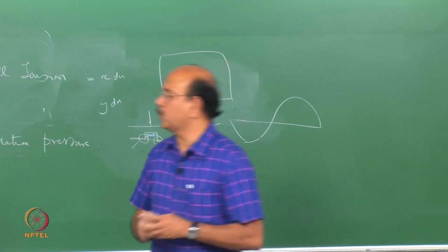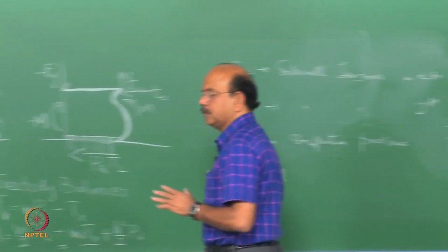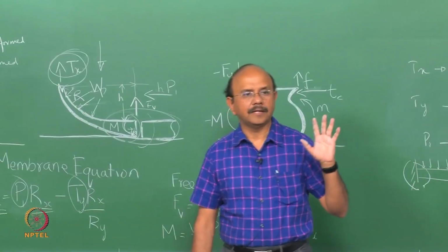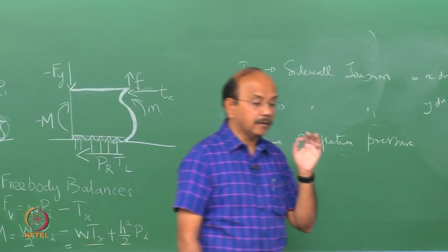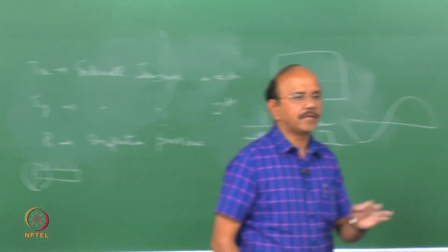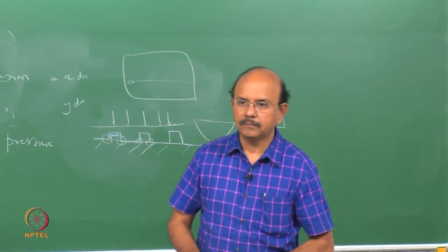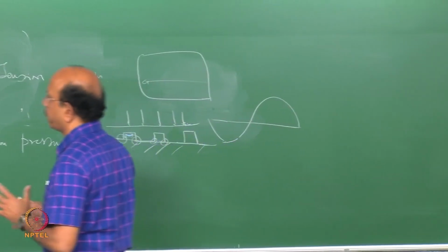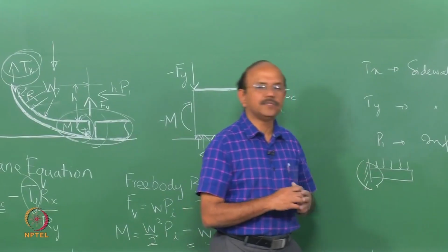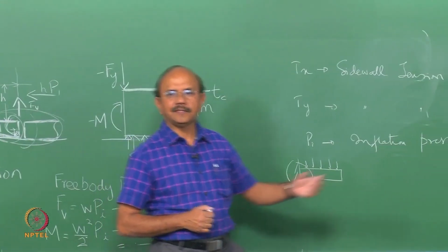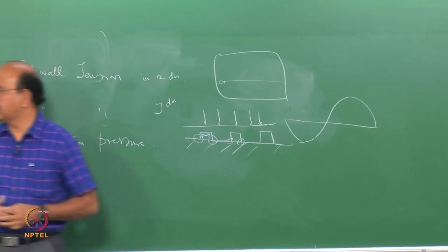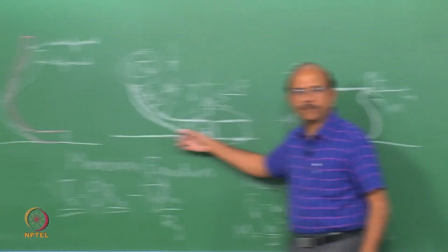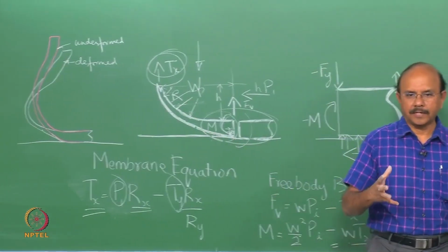Okay. Just to summarize what we said, we will continue this: the contact patch influences the interaction between the tire and the road, and though one would like it to be very uniform, it is not uniform. There are some local effects and some global effects which have an effect on the contact patch distribution.